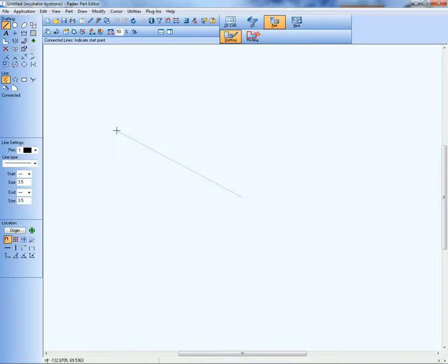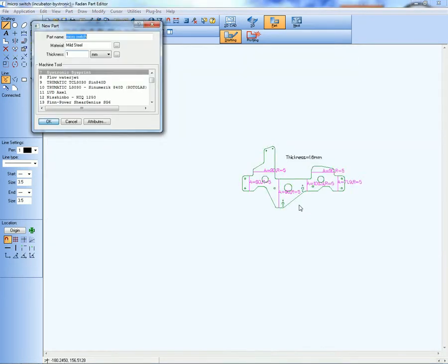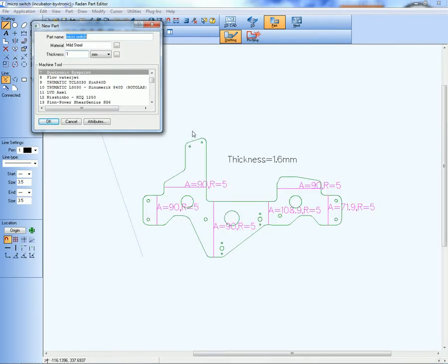It is still common for subcontractors and production engineering departments to receive data in a 2D format. Particularly for a subcontractor, this can be a problem if the allowances used, etc., on the blank are not correct. Fortunately, within the Radan system, we have the ability to import a DXF file and then convert that DXF file with the bend lines into a 3D model.